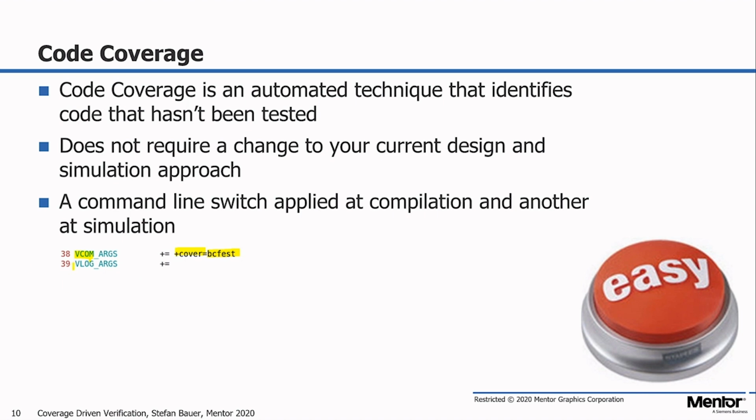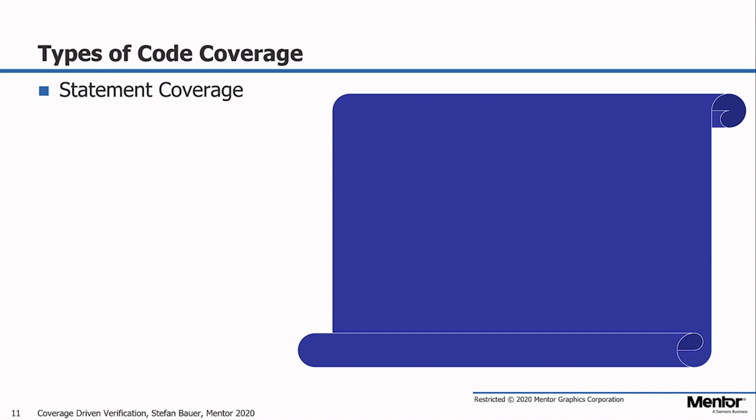By the way, you can do the same if you have Verilog. With vlog you can also add the +cover switch. For simulation, when you start simulation with vsim, you enable to collect code coverage with the -coverage switch. So let's quickly go through the different types of code coverage.